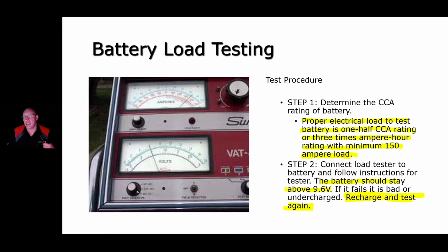It is a maintainer. It maintains the battery and supplies the electrical to the vehicle for all of the systems to be able to operate properly on the vehicle. When the engine is running, the alternator is the main power supply to the vehicle, okay? It is not a recharger for the battery. And in fact, if you are using it to recharge the battery, there's a chance that you could destroy your alternator and ruin it, okay? Because the alternator is then working way harder than it needs to be, because it's still running all the electrical components in the car as well as charging your battery. So your alternator is running at max load.